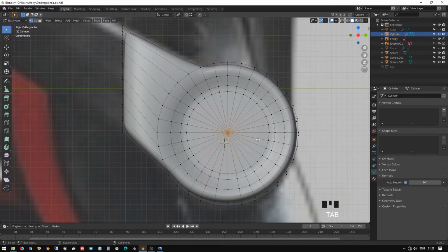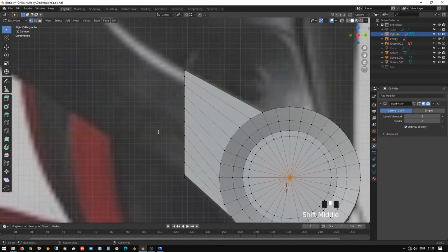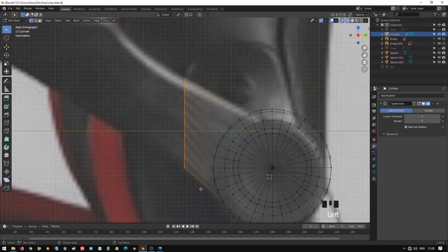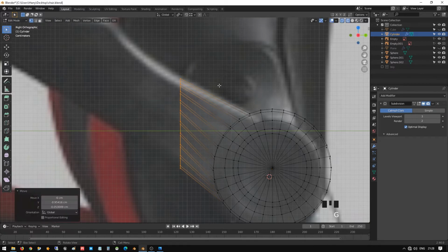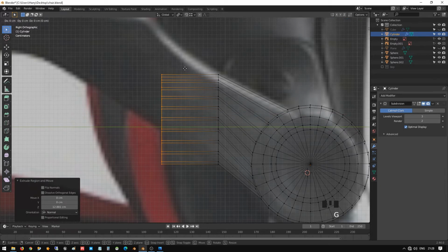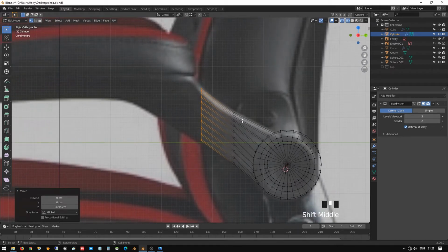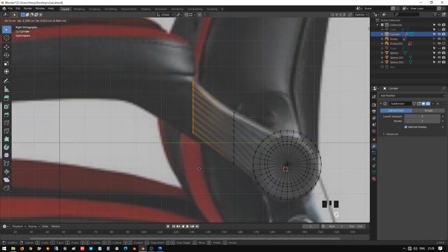Go to edit mode, and in the tool options you can untick the edit option, beveling, Shift Z. Select this, sorry, Control Z, press G, move a little bit here like this, and E to extrude, GZ. Can move like this.